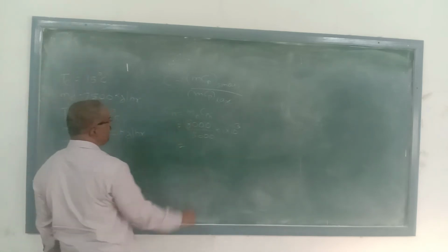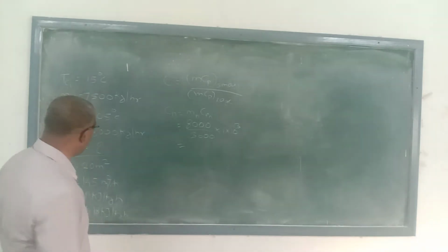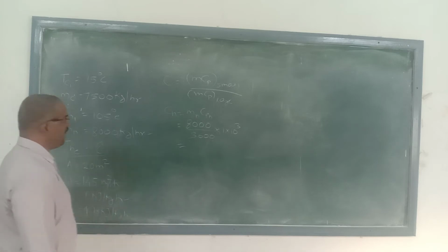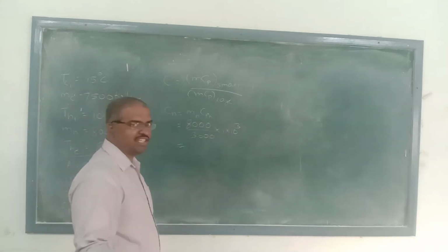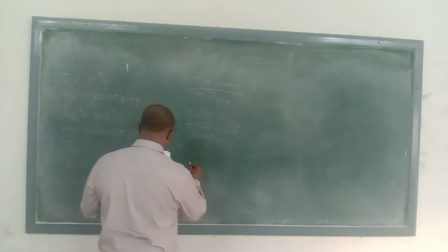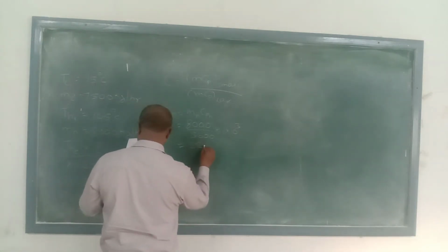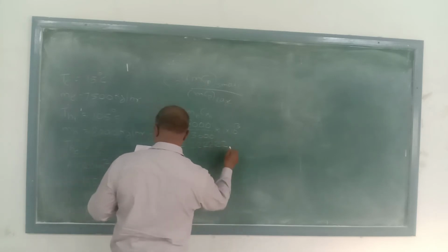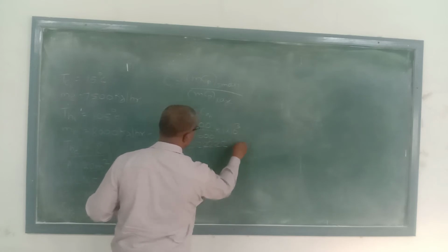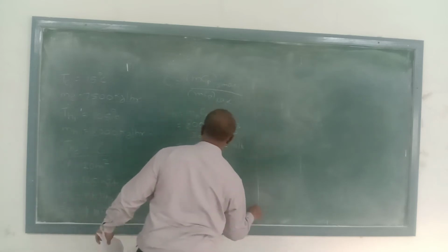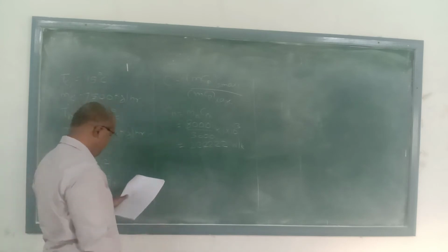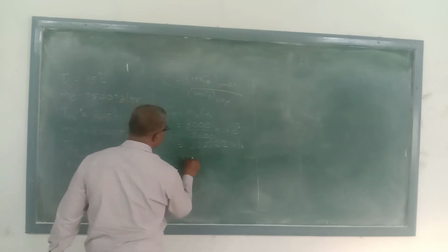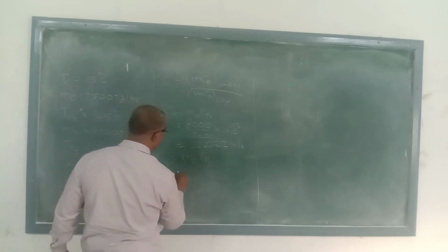Now the value of CH. See, they have given the mH value and they have given the Cp of the hot air. So we have to calculate CH, that is the heat capacity of the air. After using the calculator it comes 2222 watt per Kelvin. Next we have to calculate CC also, that is mC into CPC.